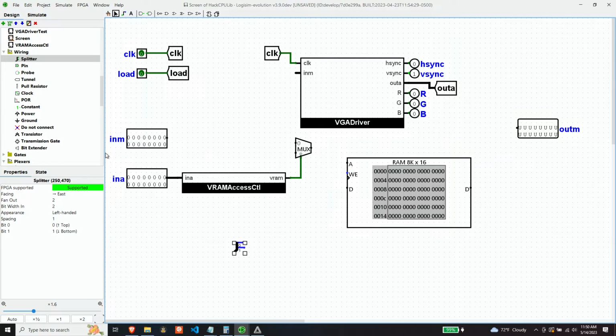And you may ask, well, why don't you use a bit selector to do this, Chuck? And I would encourage you to try that yourself and synthesize the design. And back in the comments, you can tell me why that doesn't work. I actually know why it doesn't work. There's a bug in Logisim that I'm going to file and probably fix, but I encourage you to try it yourself. And this is when you try to synthesize VHDL. It may work fine with Verilog, I'm not sure.